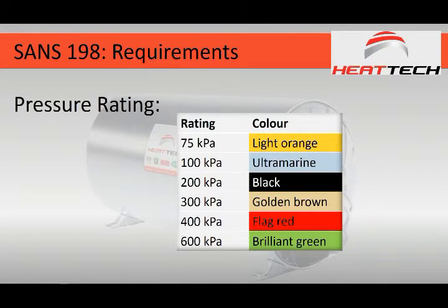And you will notice, we'll touch on that at, I think it's session number 7, where we look at the plumbing layouts as well, the correct fittings must be used, or the fittings throughout the system must have matching pressure ratings to ensure that it will actually function correctly, that even the vacuum features of the vacuum breaker will still work in a 600 kPa system.